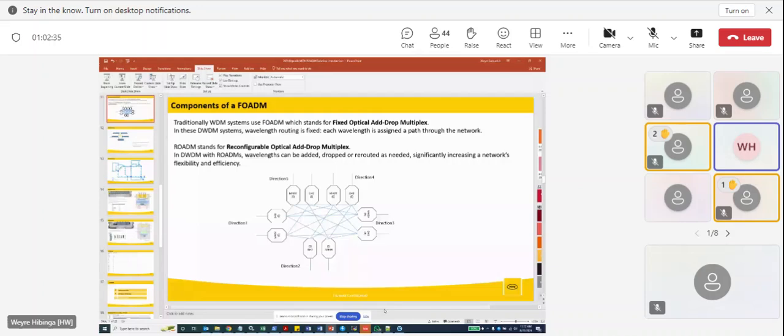So if there's any degrade, there's only one pair of patch cords to work with. However, in the old setup, you can have some lambdas okay, other lambdas not okay. In this case, all lambdas will either be okay or they will not be okay, and you only have to deal with one pair of patch cords. Okay, so basically we are eliminating the multiple patch cords we had between multiple sites, now having one. Yes.